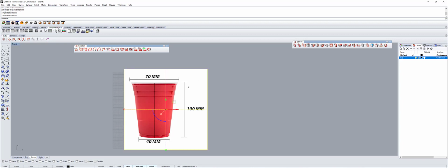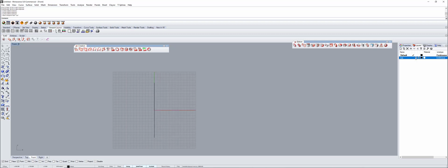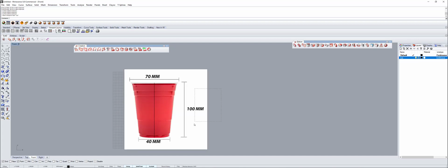So you select the picture right here, you go to the cup layer, and you just right click. It's going to show you a new menu, and over here we're going to click change object layer. What it's going to do is put this picture inside this layer. So now I can lock this layer, or I can hide it using this bulb. So now it's there, now it's not, now it's there, now it's not. It's like a magic thing.